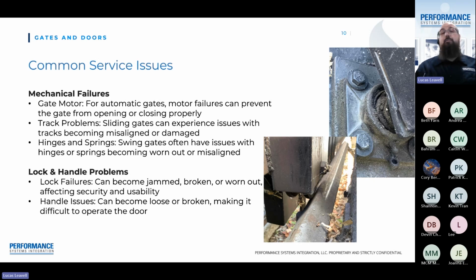These are fairly common. But at the same time, this is the type of maintenance that is often overlooked until something has already started to fail. This bearing does need to be replaced, but the gate is still working. There are other circumstances where if it's gotten to this point, it's time to replace it, or you may have a couple more days or weeks of continued use before the bearing slips out.